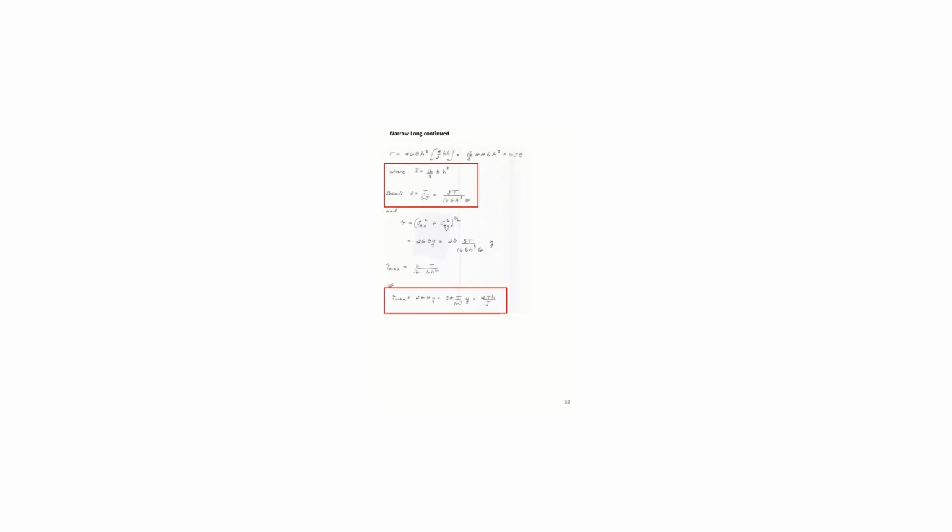So we're not going to do any more of a review than that, but that is a review for long, narrow rectangles and the equations that are used to compute the stresses, J, and the angle of twist in those. Now, it's really interesting. Many cross sections are built up of several long, narrow cross sections. And so if we have built up structures from those long, narrow cross sections, this is the expression for J that we use.